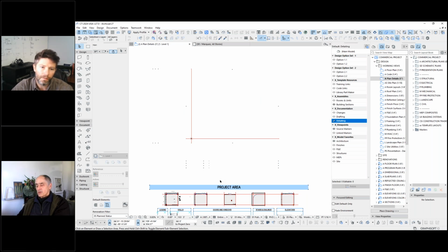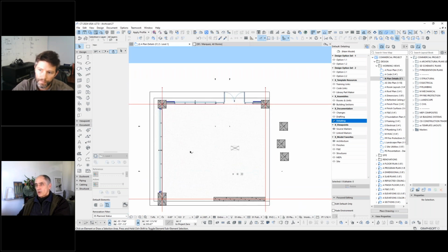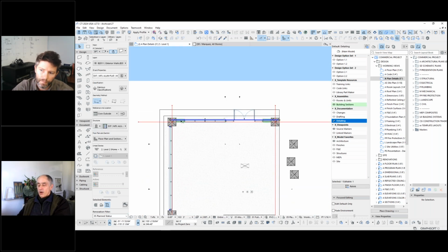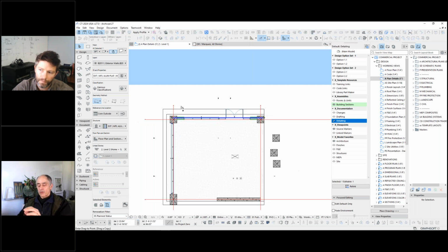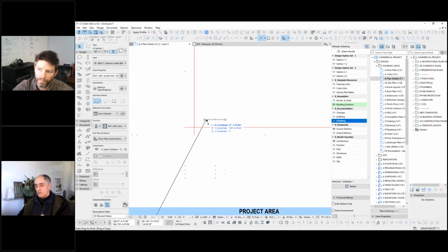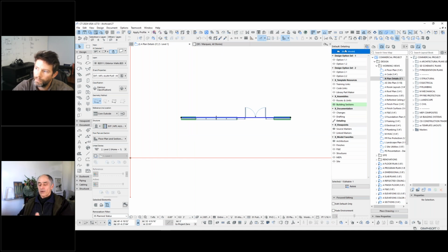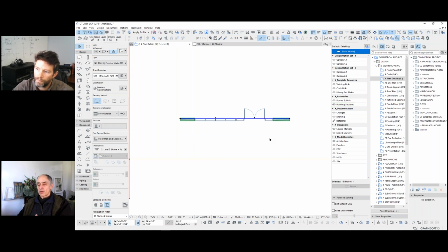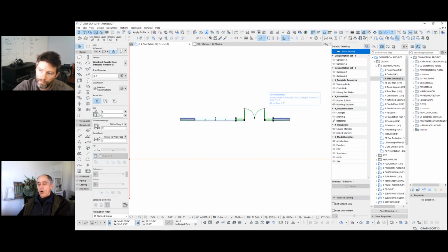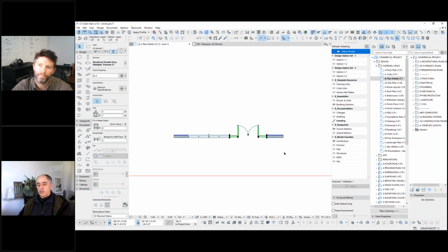Yeah, so what I figured out is the window can be set to be assigned to an option, one of the groups. Each one of these groups has typically 2 or more different options, and the window exists in one of them but doesn't exist in the other. Then the wall is either sitting plain, or if you turn on the option that has the window, it appears. And you could have a small window and a large window, or different variations there.